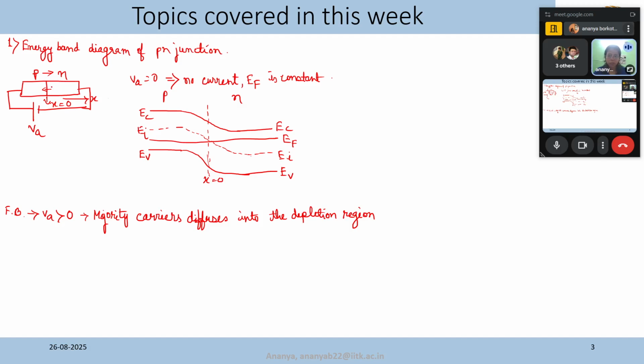First they will enter the depletion region of the N side and come to the edge of the depletion region. For all our derivations, we consider that there is no recombination or generation in the depletion region. At the edge of the depletion region the holes will diffuse, and eventually recombine in the quasi-neutral region.